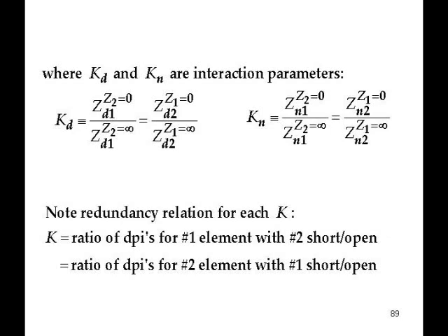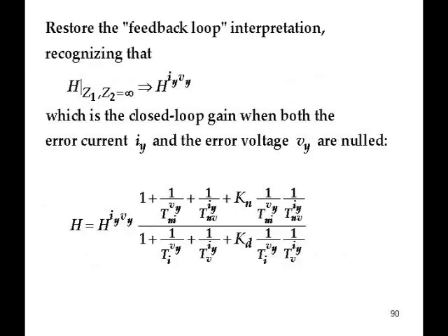And where each of those impedance ratios came from a T, now that I've extended this to the two extra element theorem, I'm going to replace the impedance ratios with the corresponding T's again. And you see the symmetries all remain in place.